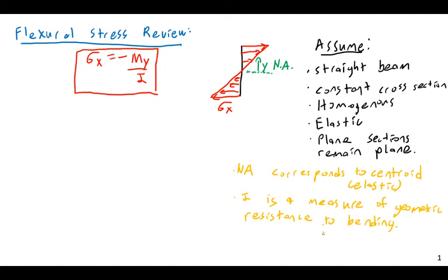For example, if we consider a very inefficient shape, imagine we built a beam for some reason like a horizontal board. That would be one of the worst cases you can imagine. And then you load it from the top like a simply supported beam. This would be a very inefficient shape. For the weight, this would have a very low moment of inertia relative to its cross-sectional area. So this is a very inefficient shape for bending.